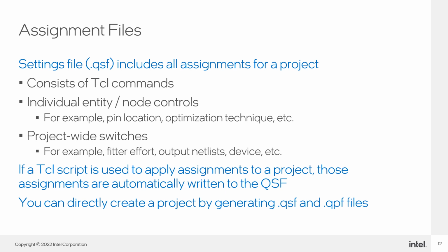If you're using command line executables to create a new project, you must use a Tcl script to apply assignments to the project. These assignments will be automatically written into the QSF file. You can also issue the commands to create a new project in the same Tcl script that applies the assignments. Ultimately, you can also directly create a project by creating a QPF, the Quartus project file, and the QSF file.